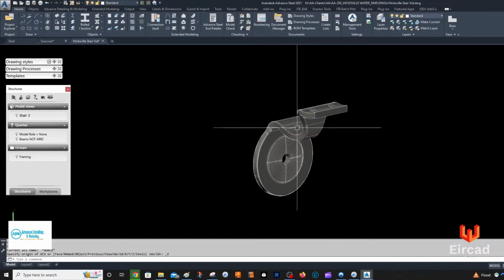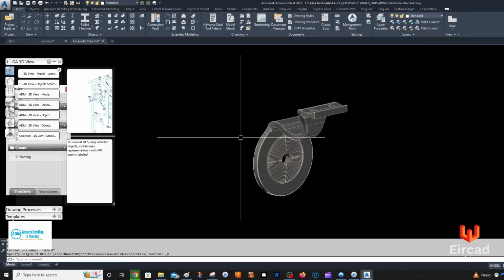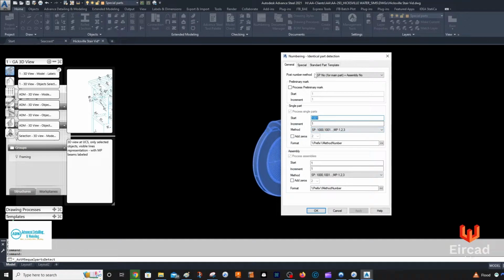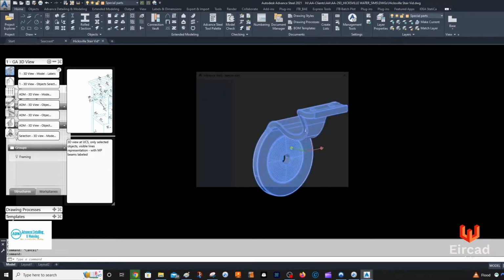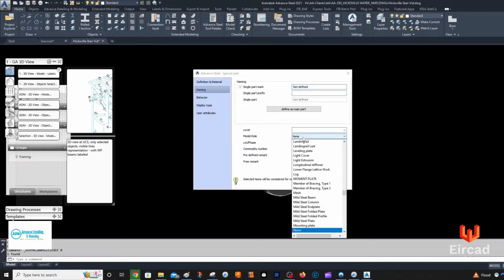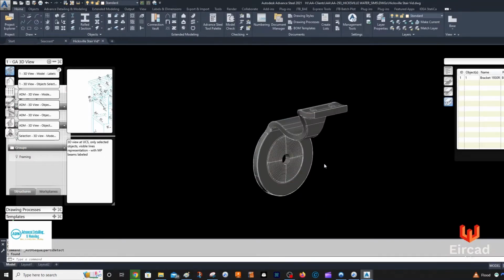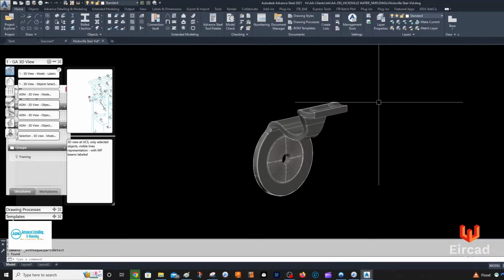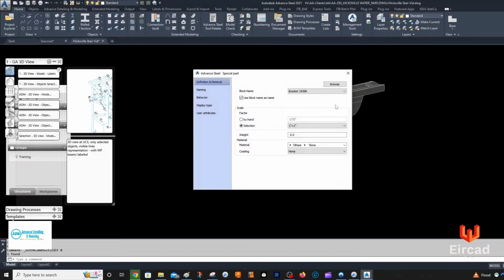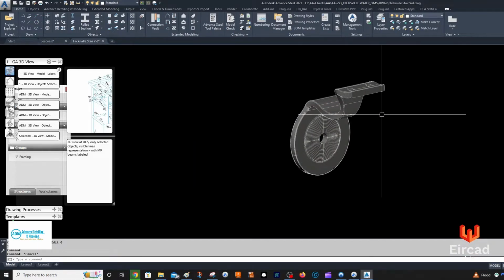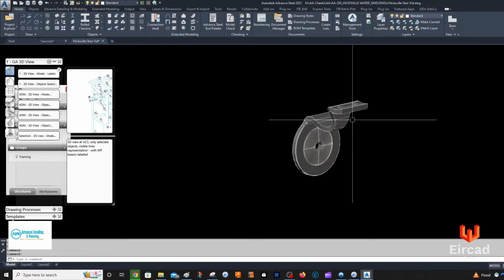So what I'll do is I'll just set my UCS, and then I'll come in here, and what we want to do first actually is let's number this. So let's go in first to make sure it's set as a bracket, and let's set this as a bracket, and then we'll number it. Okay, BR1. So let me just go in here. I already have a BR1 in this drawing, so I've created a drawing already, BR1, but that was actually I resaved it, so it's fine.